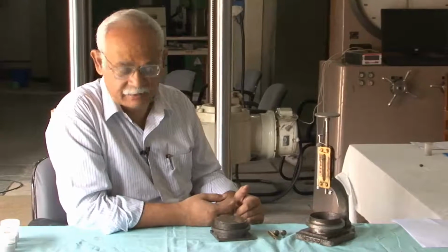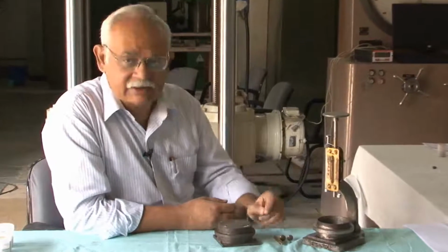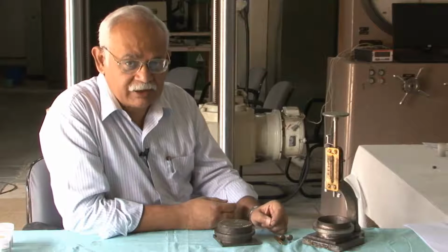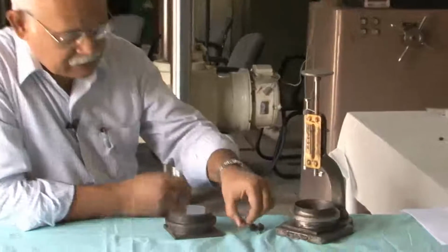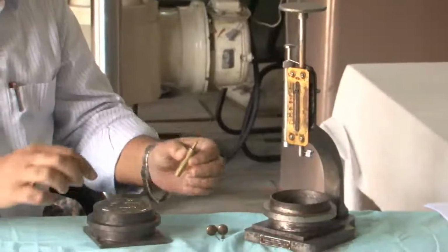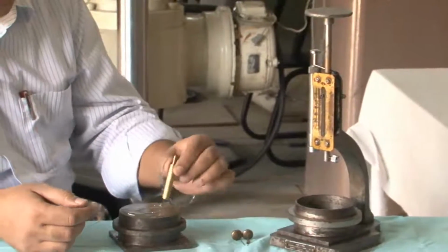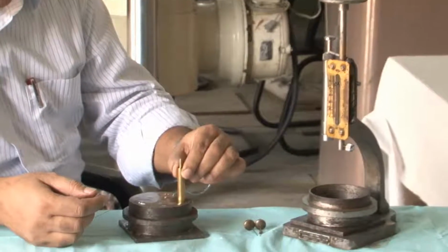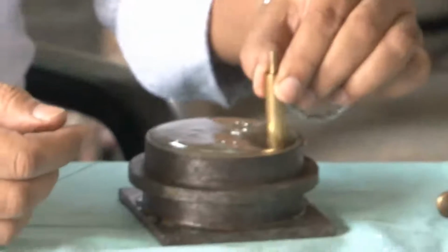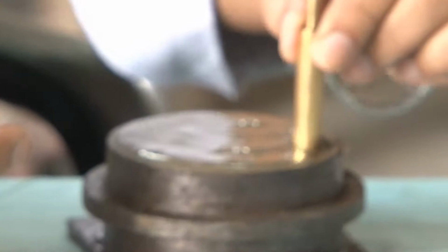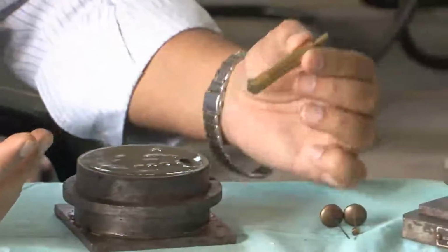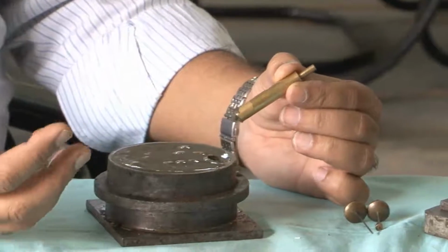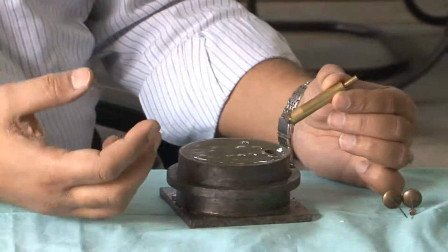One of the important parameters for cement is consistency, standard consistency, setting time, initial setting time and the final setting time. Now, all these tests are in principle based on penetration resistance. That is a paste which is here in this mold. If the penetration resistance to this for a given load is high, then the material has set. If it does not offer any penetration resistance, then the material is still very close to being a fluid.